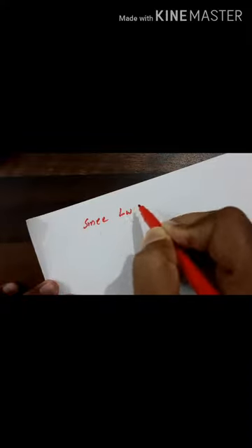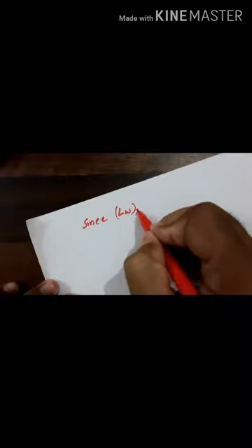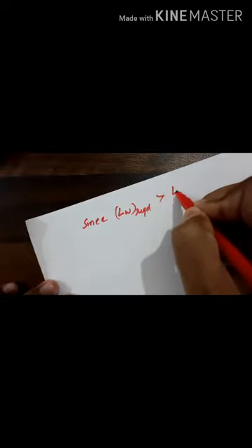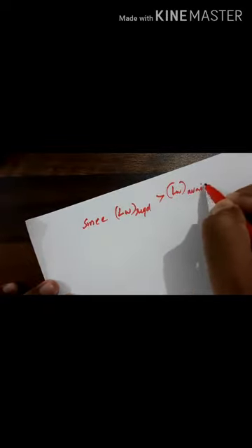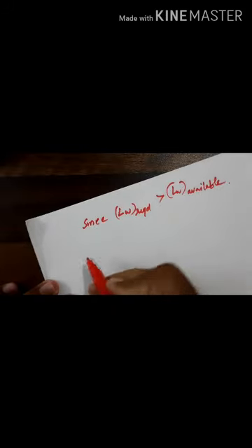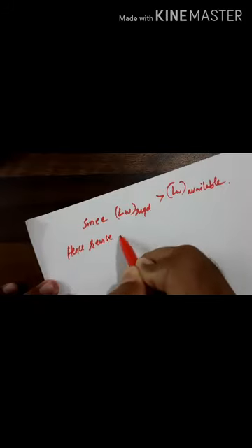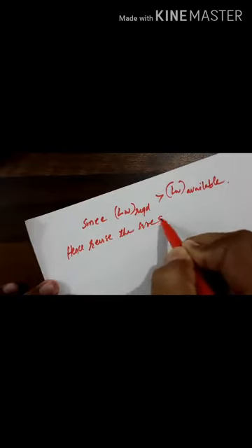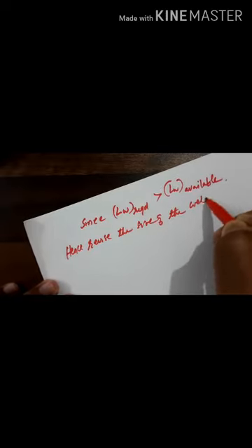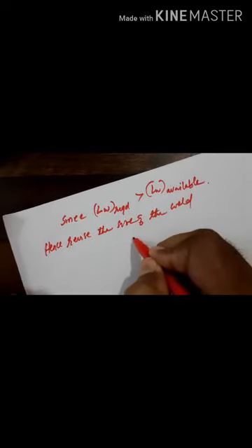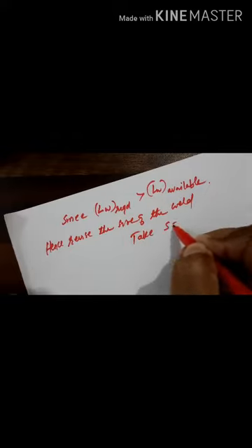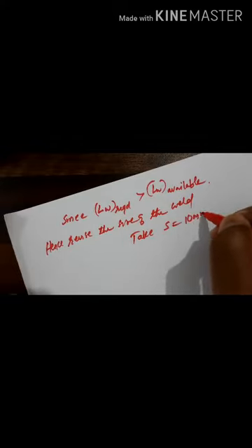the weld. So, you can write one line: since the length of the weld required is more than the length of the weld available, hence revise the size of the weld. You have to revise the size of the weld. Take the size of the weld as 10 mm.